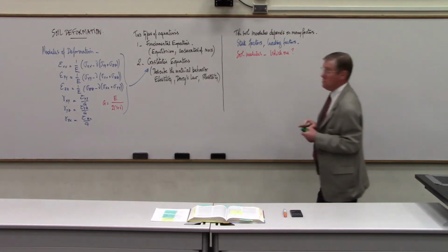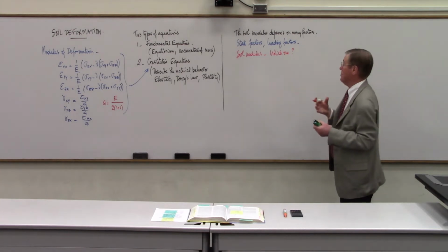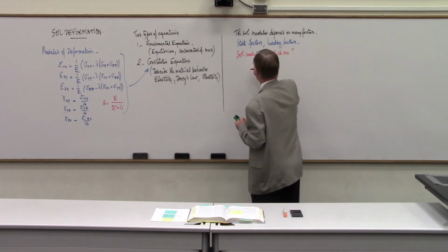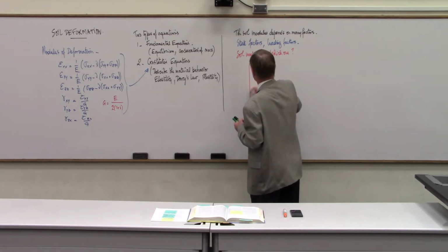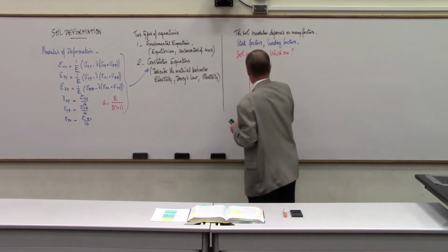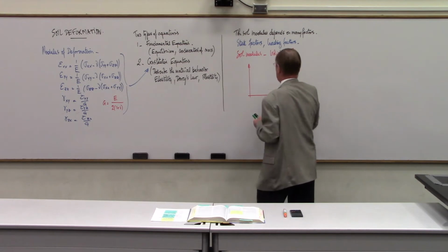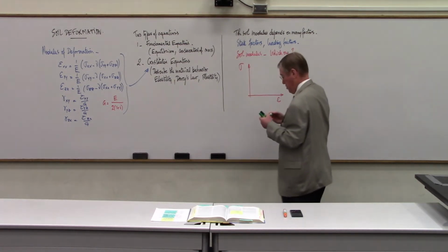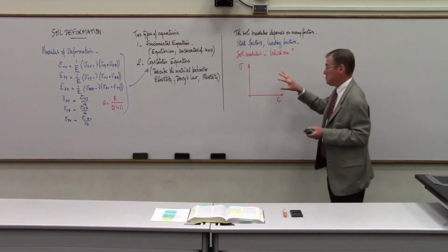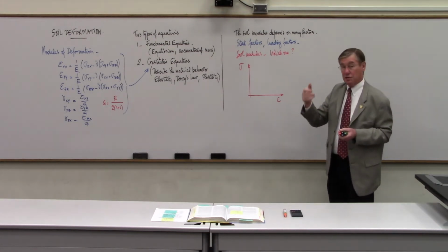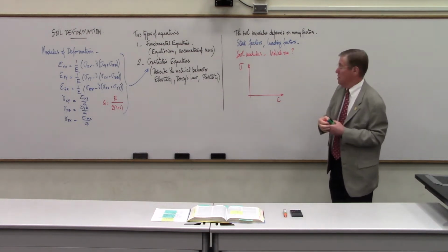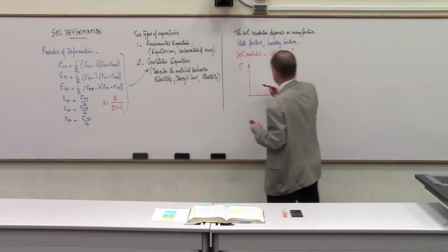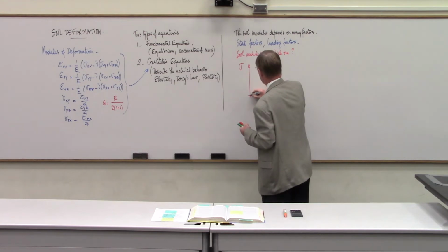The reason this is an important question is that this modulus is associated with a non-linear curve. So we have to be aware of, and I'll take a sigma and epsilon representation, understanding that, as we mentioned in the last lecture, the slope of that line is not the modulus unless you run an unconfined compression test.